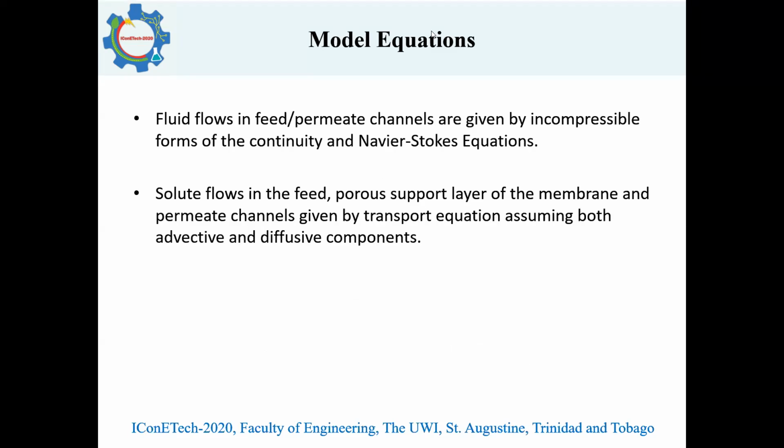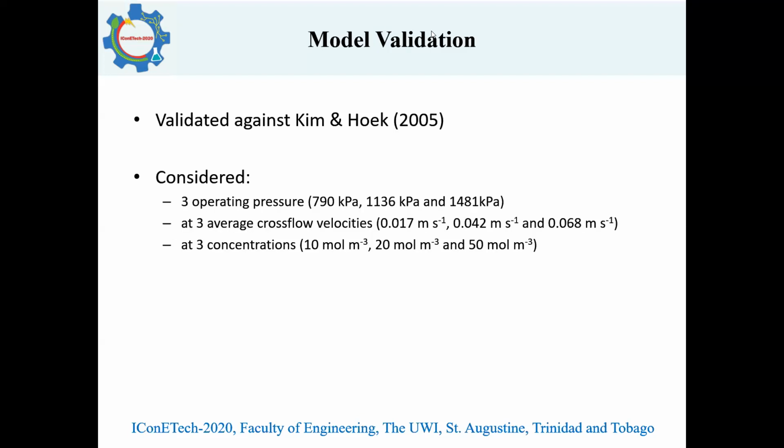Right. When we were specifying our equations for our permeate and feed channels, we assumed that the channels are given by the incompressible forms of the continuity and Navier-Stokes equations, and that the solute flows in our feed, porous support layer of the membranes, and permeate channels were given by the transport equations, assuming both convective and diffusive components. Right. So once we had developed our model, we had to validate our model.